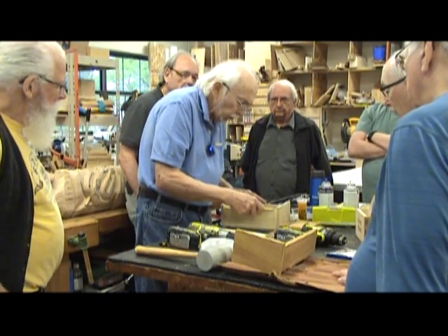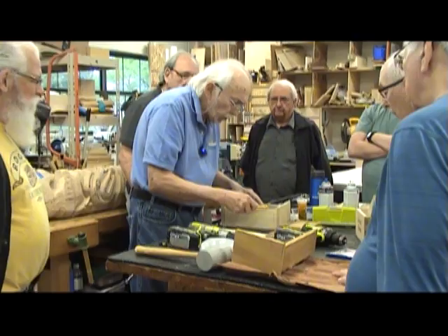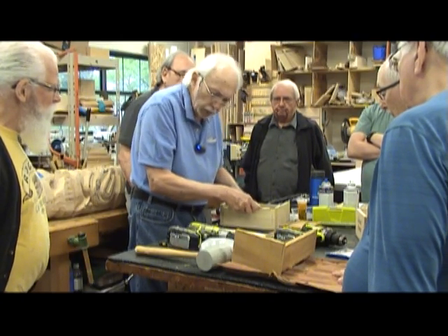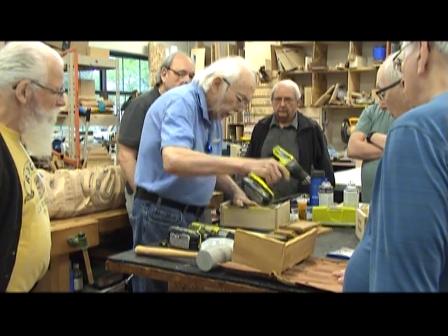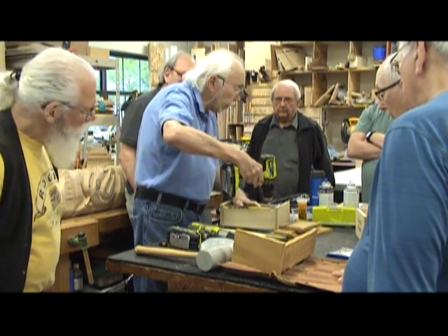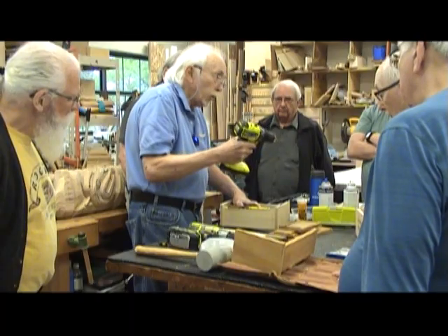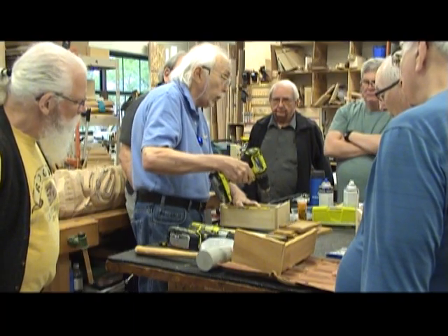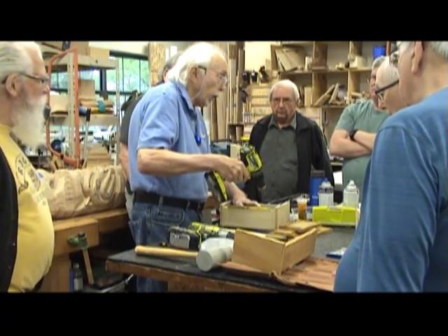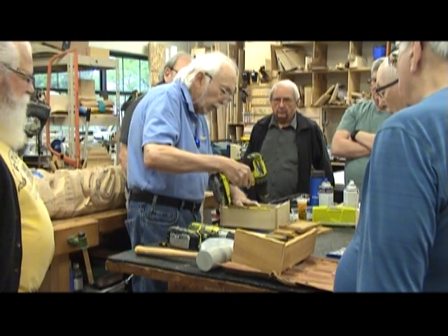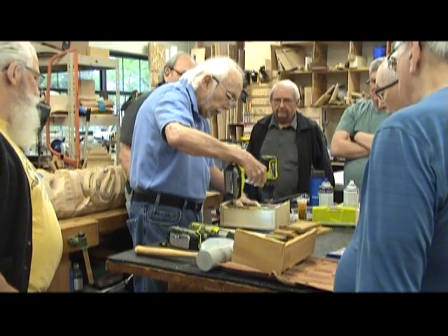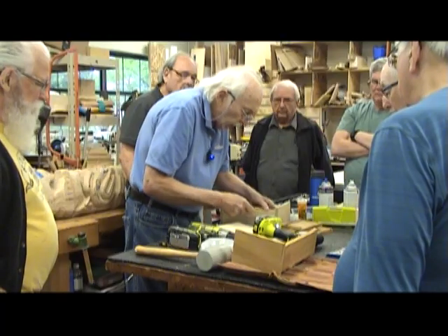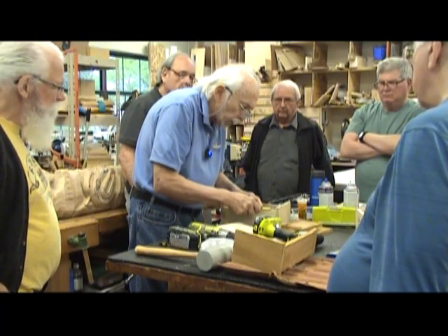So in going through the steps of mounting the hinge, I will typically do that for the center of the first one. And then I pick a drill bit that's just slightly smaller than the screw itself, and that's important on the hardwood. These little screws will break with the least amount of pressure. But I usually put the first screw in.